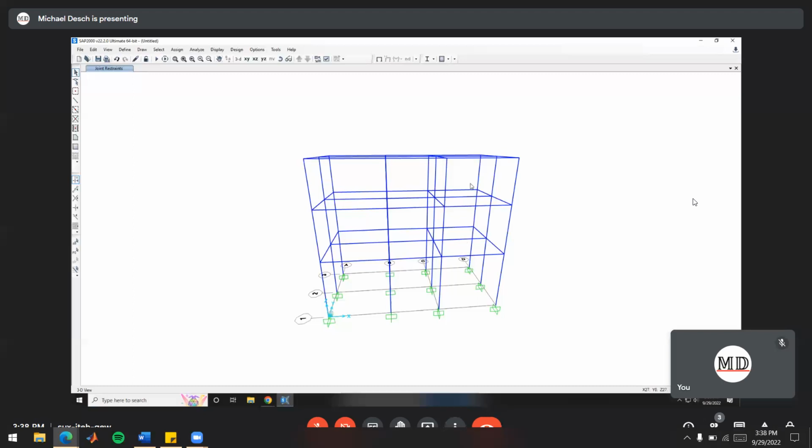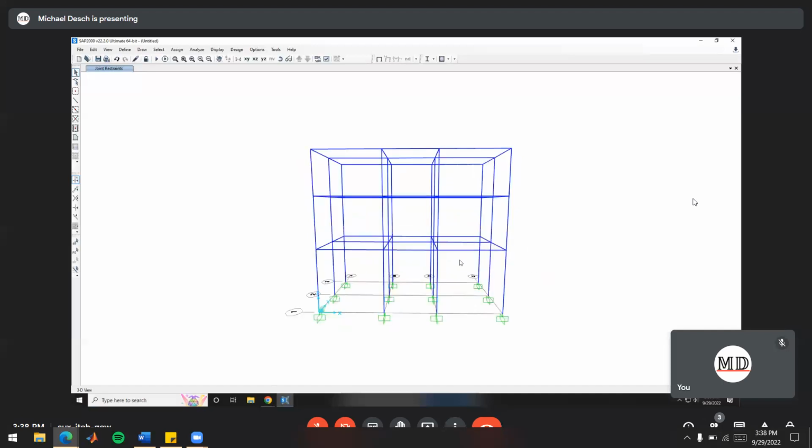Okay, so now that we're all ready with this, we've got our load set up, we've got our combination set up, we can start applying our loads. So we want to orient our structure in a way where, like this, I find is pretty helpful for how I want to select the loads here, where we can go and select all of the beams in our kind of X, Z view here in all 3 of these frames that are in the Y direction there. And once we have those selected, we should have 27 frames selected. So you can read that in the bottom left there. Make sure you've got everything selected that you want.